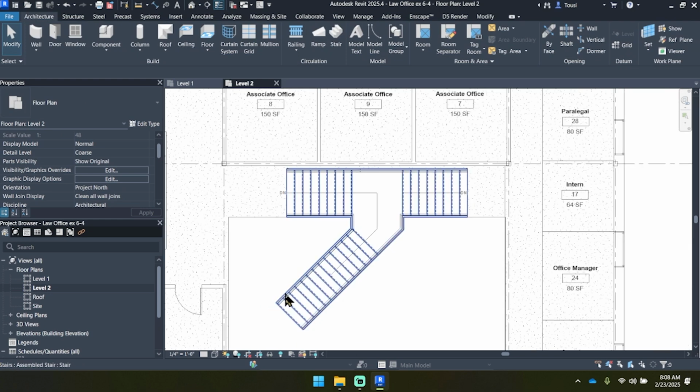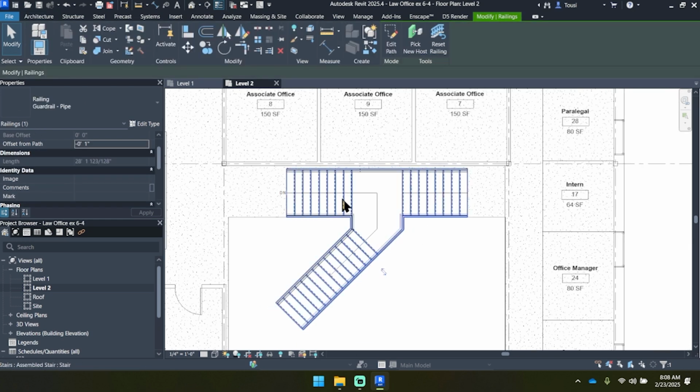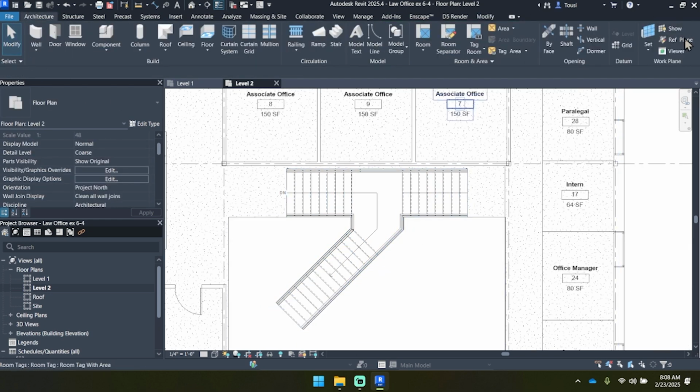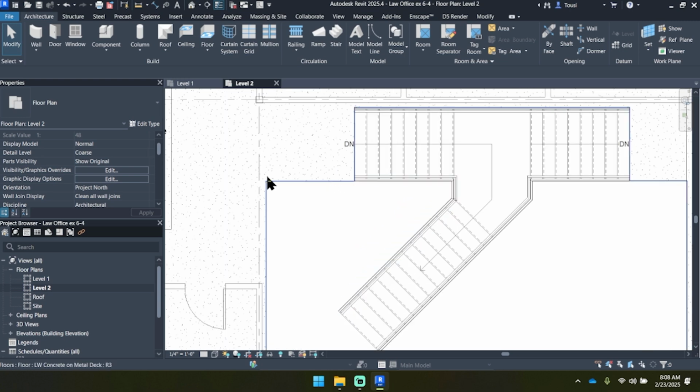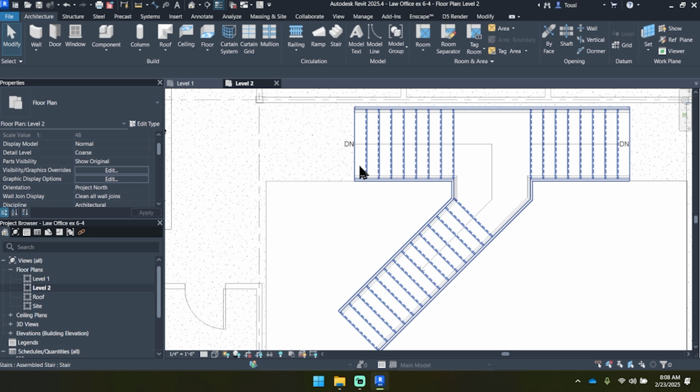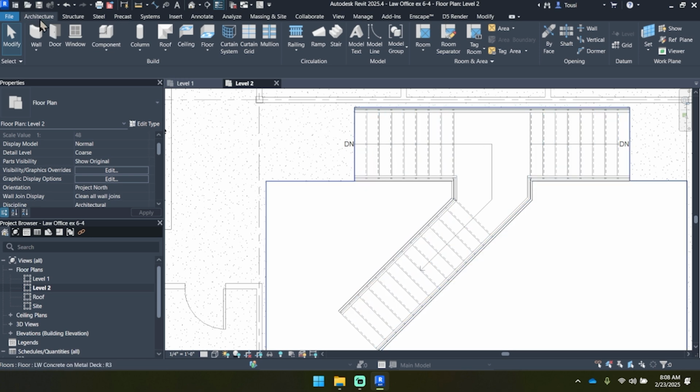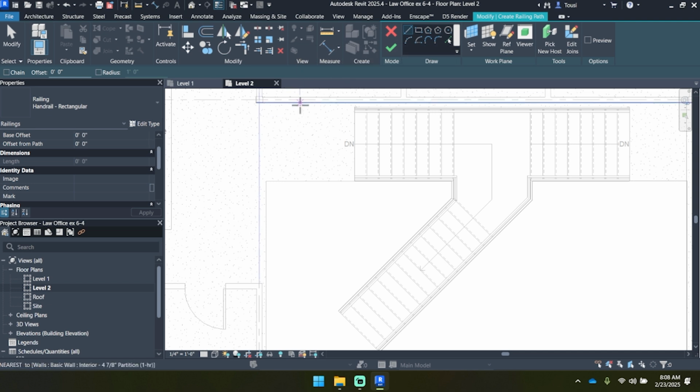Now we currently have railings coming up our stairs automatically created for us, because when we were drawing the stair, we came over to the railing area and told it to assume that, but now we have an unsafe condition here where the second floor has an opening because the stair did not assume to add railings on the floor where it's meeting. So we're just going to draw railings by themselves. Railings can come with stairs and ramps automatically for you, or you can come to the Architecture tab and under the Circulation panel, get the Railing tool going, and that will go right into a sketch mode.